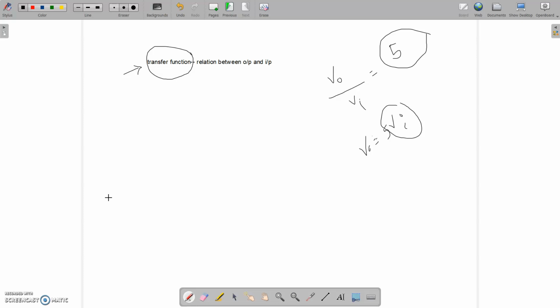If we want a low pass Butterworth filter, I have this resistor and capacitor, right? This was my input here, and this was my first order low pass filter. Now let's make it second order. To make it second order, I have to add another branch, like this, with a resistor and a capacitor. This is my other branch, two branches. Now we want to mitigate the gain problem, so we add an op amp here and make it an active filter.